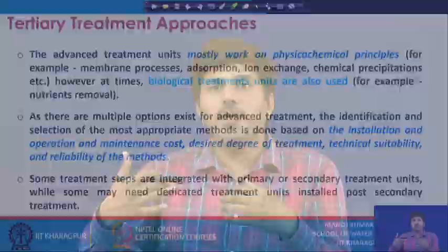Okay. In case of biological treatment also, we discussed that for the removal of dissolved organics we can go for the activated sludge process, trickling filter, rotating biological contactor, anaerobic processes, and there are a few more which we will discuss next week when we go for the integrated treatment schemes which are used these days. So, there are a variety of processes for the removal of a specific type of contaminant, and the same is seen in the advanced treatment process as well.